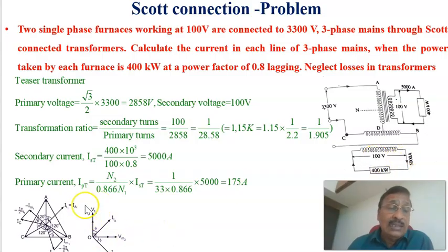winding load as such. Therefore, this is the phasor diagram corresponding to the secondary, and that is reflected here, and that is added. This is the vector corresponding to the current due to the main secondary voltage. To that one, half of the teaser current is vectorially added, and then you get the line current in phases B and C, as I already explained in the previous slide.